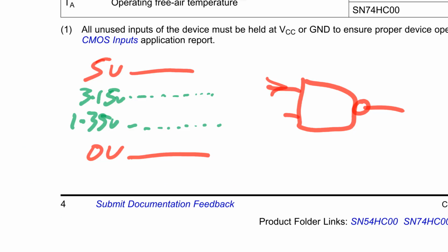So this is the threshold level of our digital logic. If our input signal goes up like this, let's say it shoots up and comes back down, it never got to a point where it actually reached this threshold here. So let's say we had an input which goes up just like that for a split second, then our input here is actually going to register as a logic high. And likewise, if our signal just went down like that, as long as it goes through that threshold level there, it is recognized as a logic low.